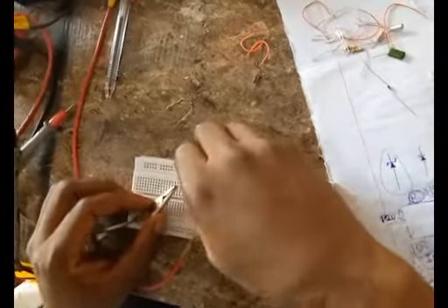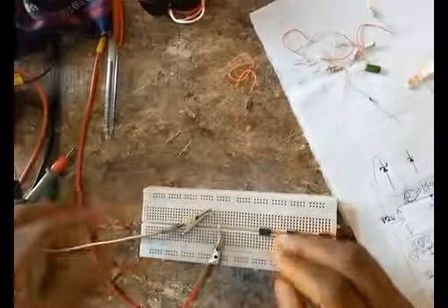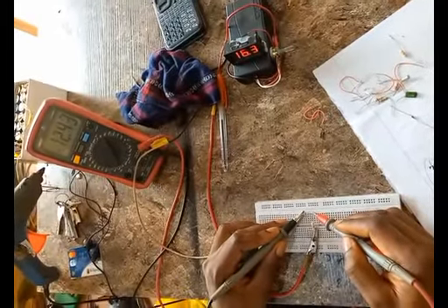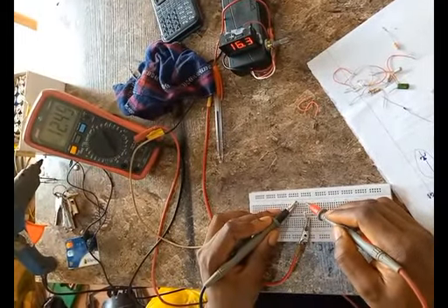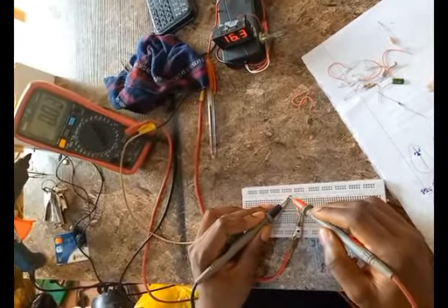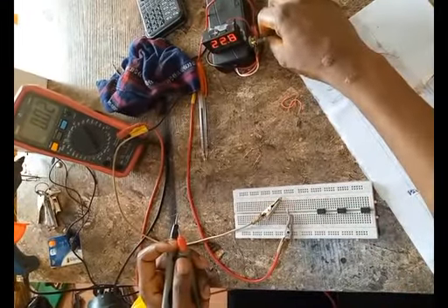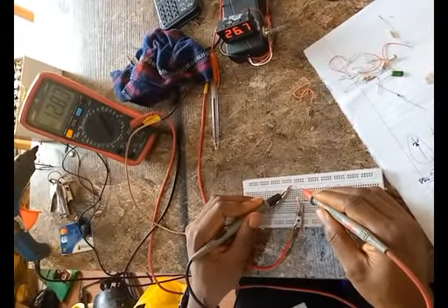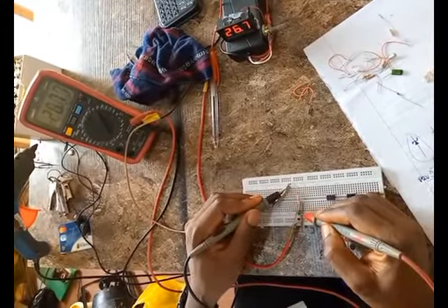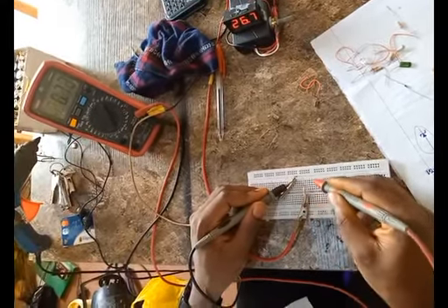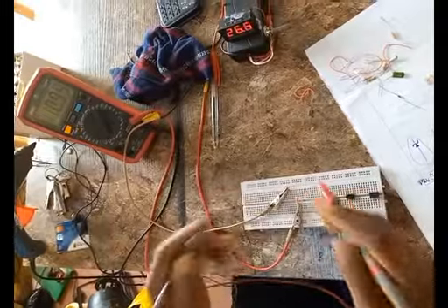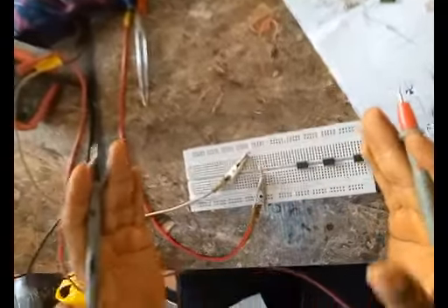Let's put it here. Okay, so let's see. 16 volt entering, and this is 12 volt output, because this is a 12-volt Zener diode. Now let's increase the input to maybe around 26 and see what still happens. Input 26, and what you get at the output is around 12 volts. So you see that it clips it at a particular voltage regardless of what is entering.